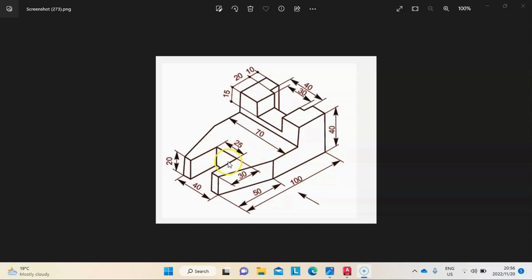There is also a groove inside there. It will be indicated by just one hidden line. That hidden line represents the edge that passes through that corner going down. That edge actually covers that one there in that plane. So you will also see another hidden line there representing that edge and the edge that passes through that corner. And also here there will be another hidden line going down from that corner. So we also have to indicate all that.